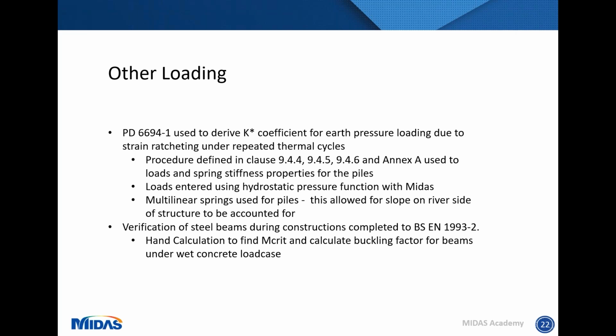and then we also used multilinear springs for the piles. This was mainly to account for the different stiffness values that you would have under contraction and expansion, as the riverside has a slope that needed to be accounted for.